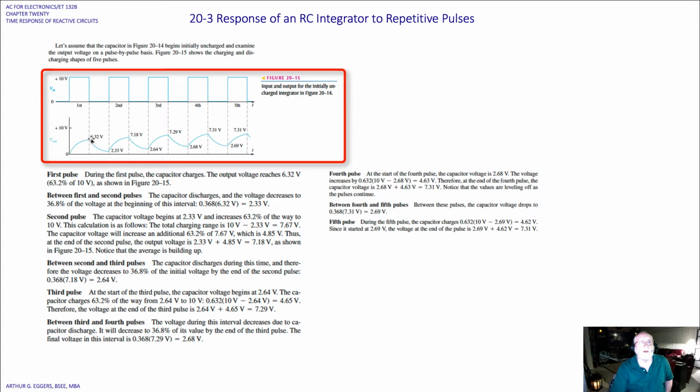So we can see the circuit acting on that capacitor, being charged not fully and then going into the next charging cycle. During each discharge cycle going into the next charge cycle, we've got a little bit of voltage left over in the capacitor.